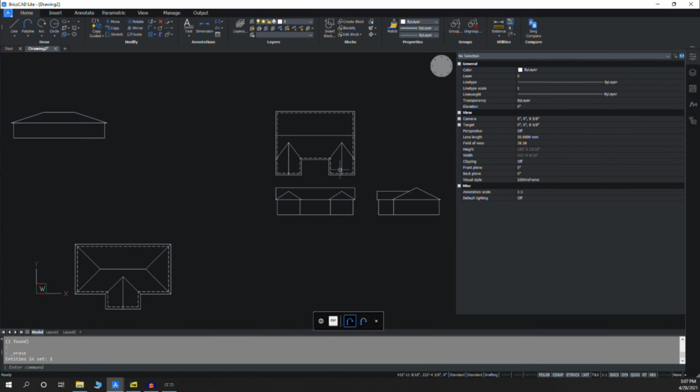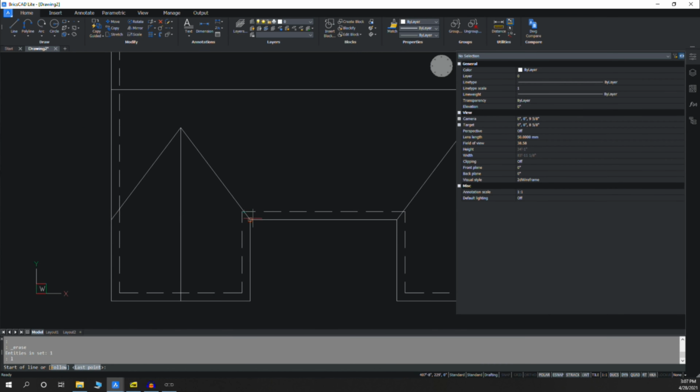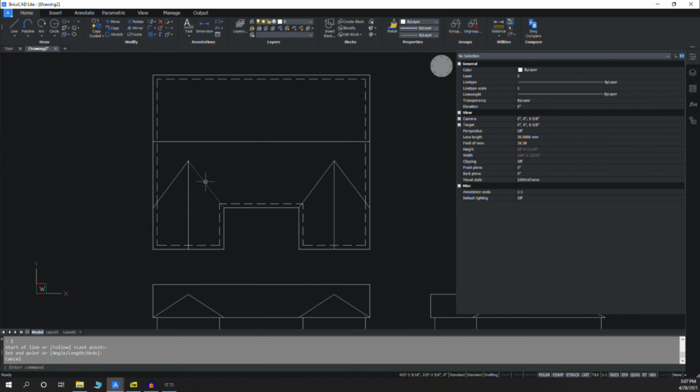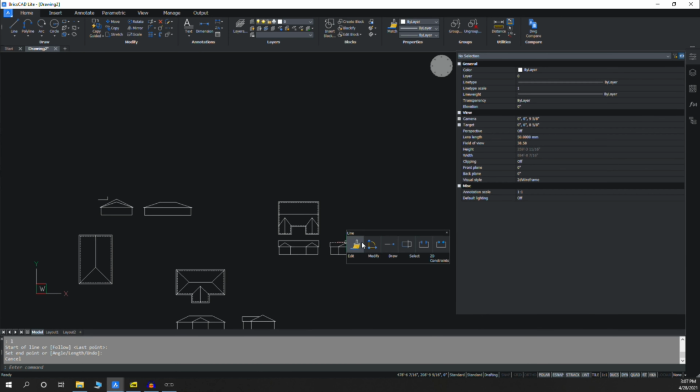And then I even showed you the really complex one where you've got two different roof pitches interacting with each other, and I showed you how to make reference lines that follow the ridge line of the two different pitches to get the actual angle of that weird valley.